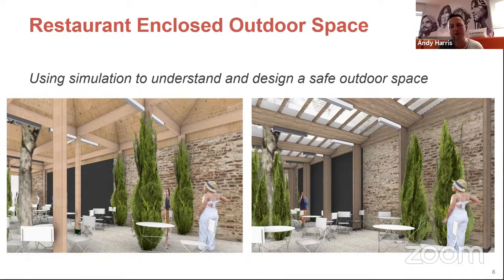So one of the big challenges we had with this outdoor space, and the reason why it had to be enclosed, is because the buildings around it are quite high, and it's not quite an alleyway, but the courtyard had a lot of gusts of wind. It was very uncontrolled air. So we really wanted to control the air, but also have a really high air change rate within that space, around 20 air changes per hour we were aiming for, to try and extract as much air out of there as possible without it being uncomfortable. So if you move to the next slide, Reese.